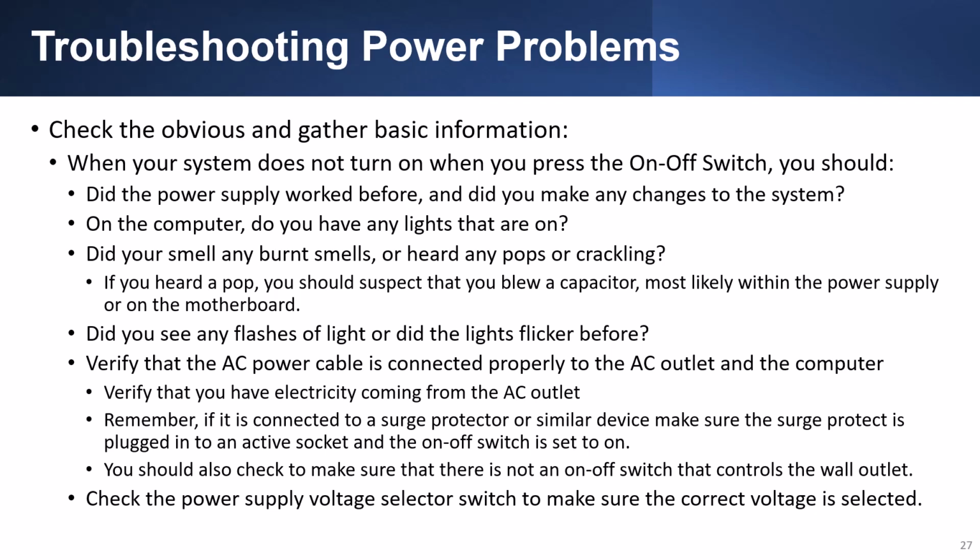When troubleshooting power problems, check the obvious and gather basic information. When your system does not turn on when you press the on-off switch, ask: Did the power supply work before, and did you make any changes to the system? On the computer, do you have any lights that are on? Did you smell any burnt smells or hear any pops or crackling? If you heard a pop, you should suspect that you blew a capacitor, most likely within the power supply or on the motherboard. Did you see any flashes of light, or did the lights flicker before?